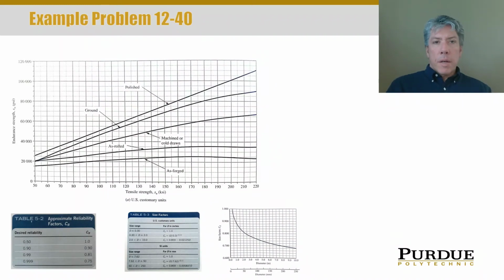So now that you've seen how to calculate all of the loads along the length of the shaft that we're designing, you know what the moment is everywhere, you know what the shear is everywhere, and you know what the torque is everywhere in the shaft. And those are the loads in the shaft. Those are the loads that the shaft has to be sized to support.